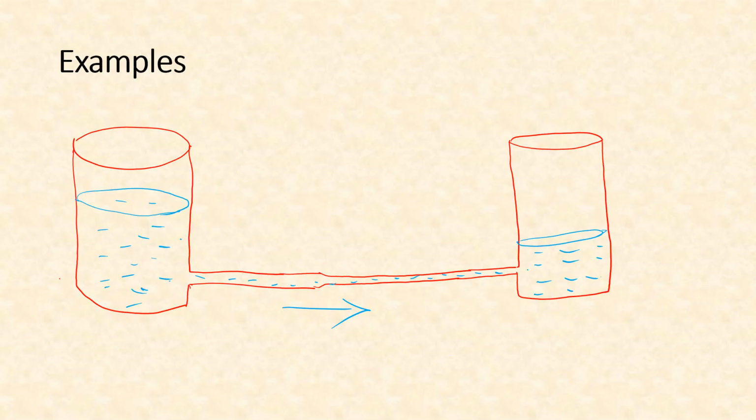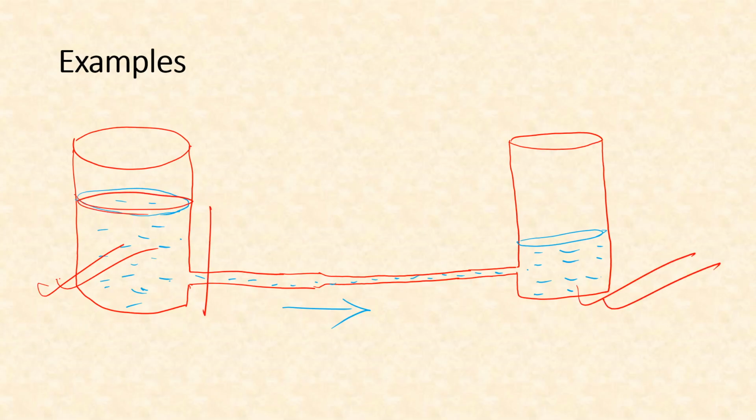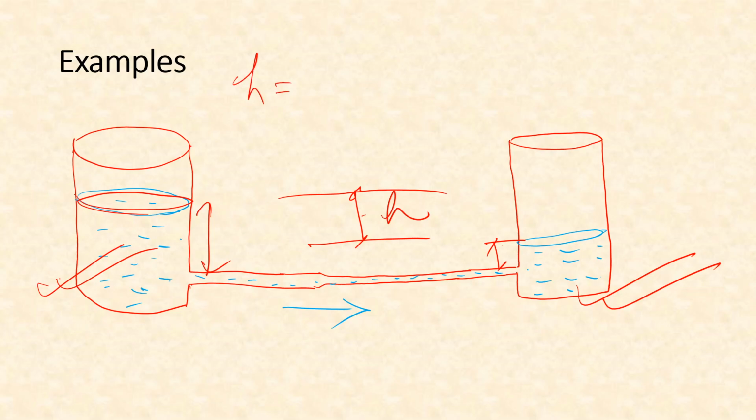it's a very simple example where we have one tank and another tank. So here the water level is slightly above, so head is higher, here head is lower, and the difference between them is suppose H, and this H is equal to the sum of head losses between these two pipes, that is HA plus HB.